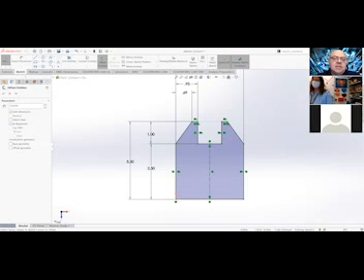By seeing it, then we understand it. So if I bring my cursor now over to my center line that I did right down the middle, and I click on that, let's look at what's happening here. It's set for 5/8. It's going bidirectional, so it's taking this center line and going 5/8 to the left and 5/8 to the right. So we need to change that.